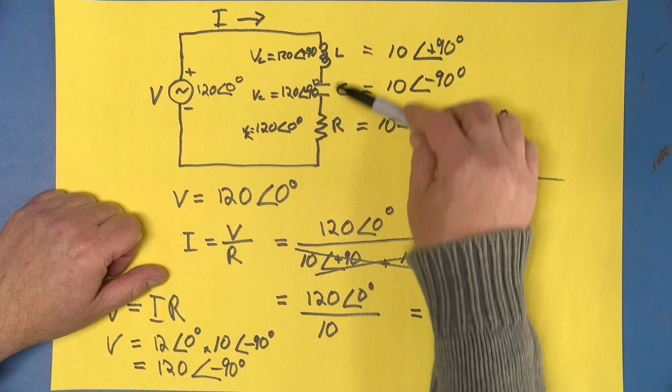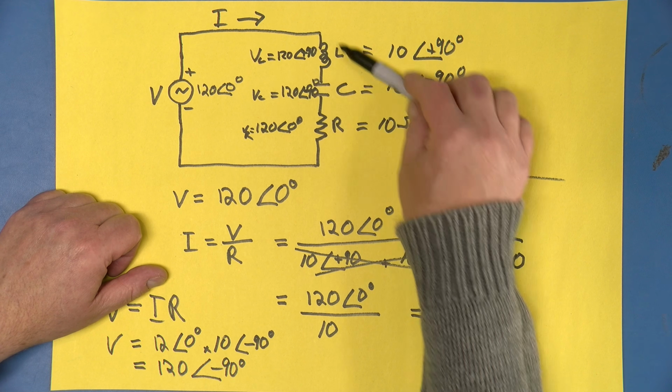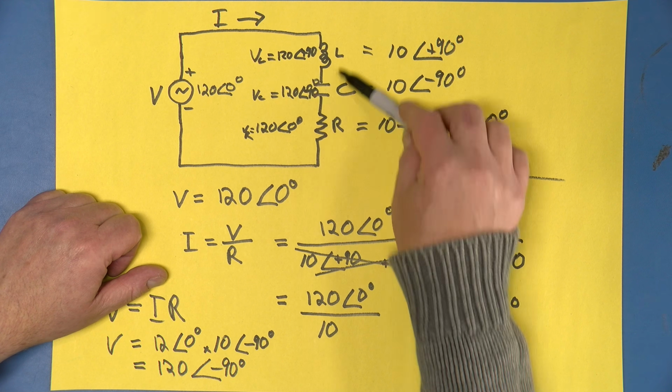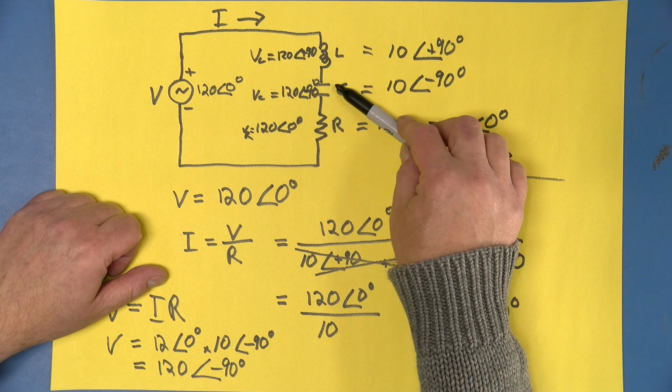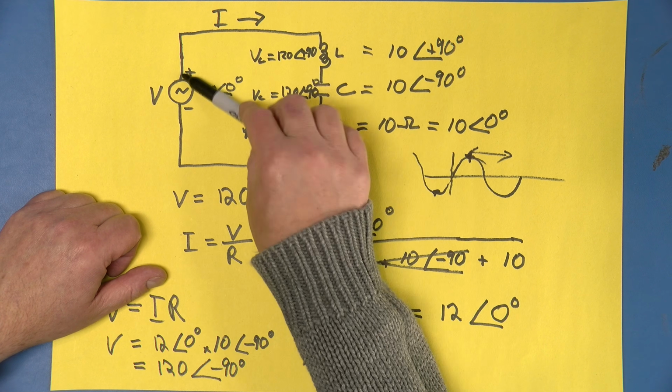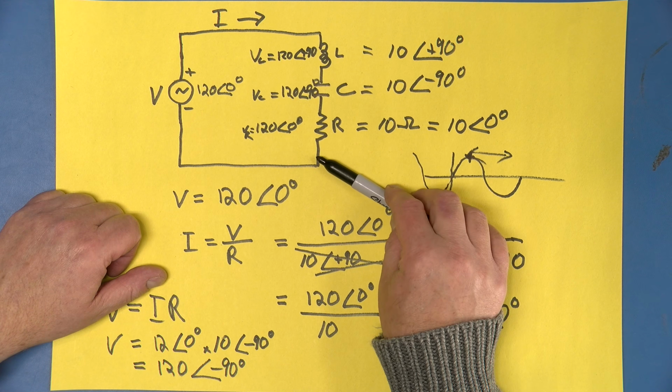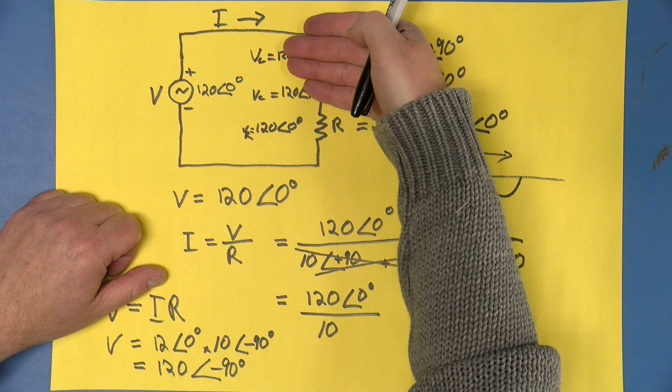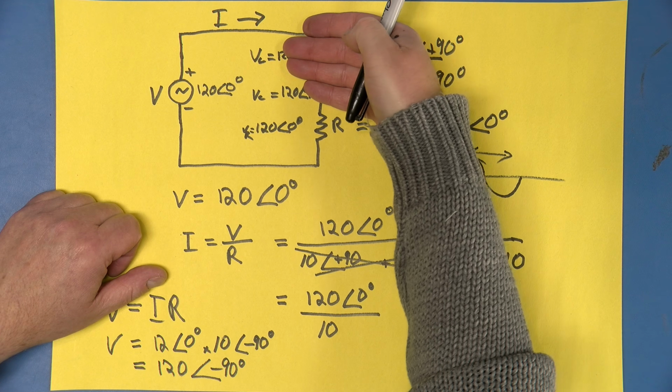So there's really 0 volts across here if there's no nonlinearities or non-ideal behavior of these components. There is no voltage across here. That means the full voltage from the source is across this resistor. It's like these two things never happened at all.